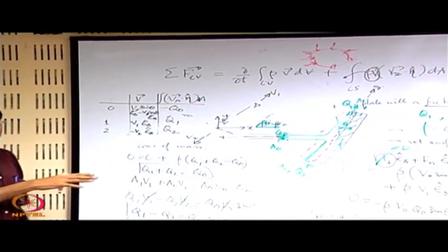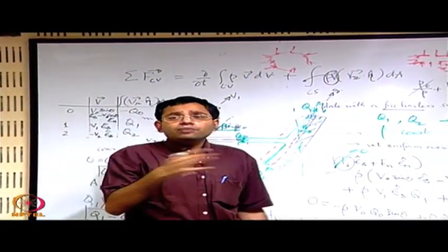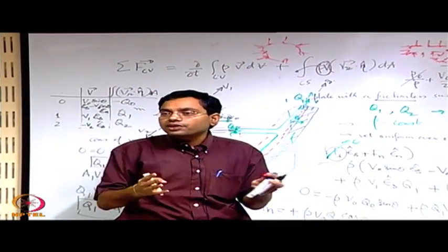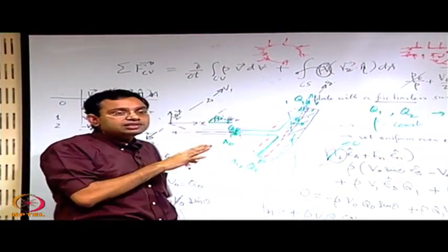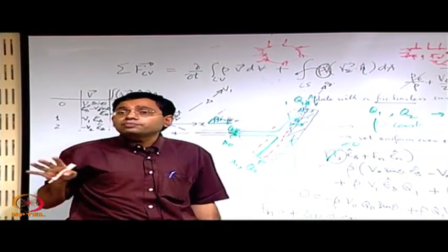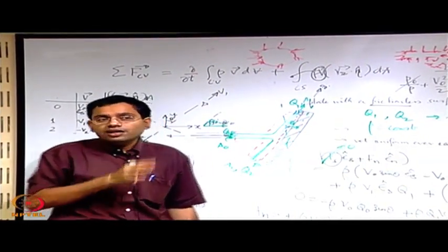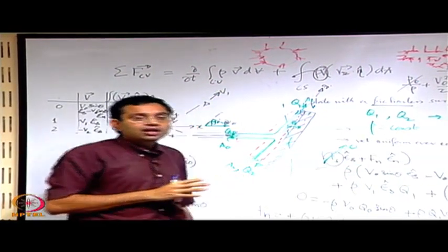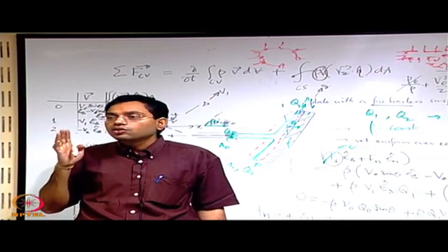So if that is the case, then if there is a variation of pressure only, that will matter to a resultant force, but if throughout it is atmospheric, then it does not matter. Therefore our negligence of the pressure in this case has not mattered because it is a uniform pressure, and that is why you will see that what is important for us is not what is the atmospheric pressure, but the deviation from the atmospheric pressure, that only can give rise to a local force.